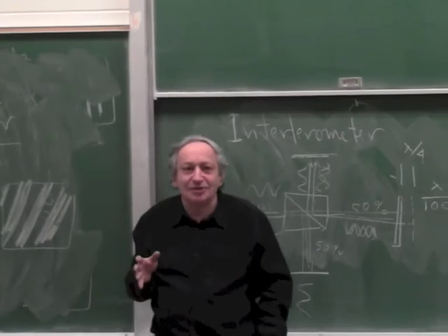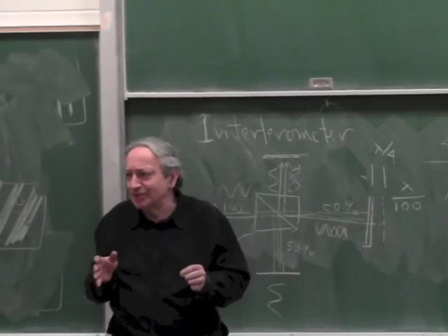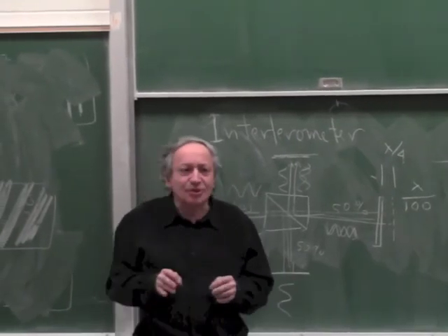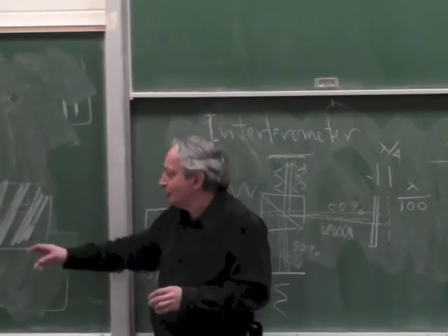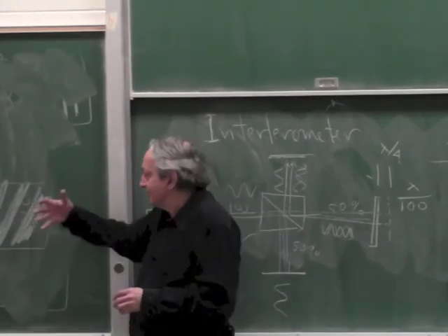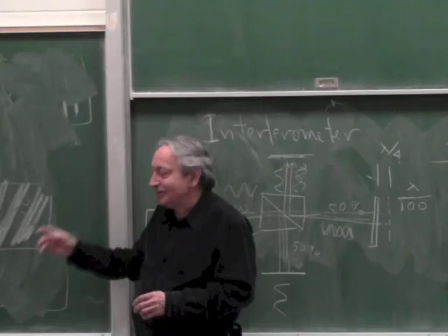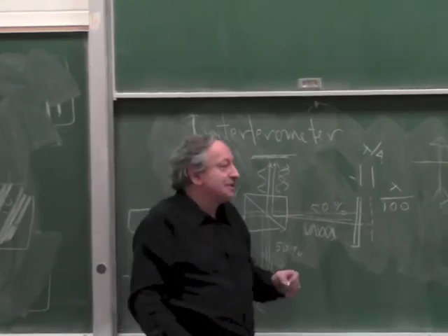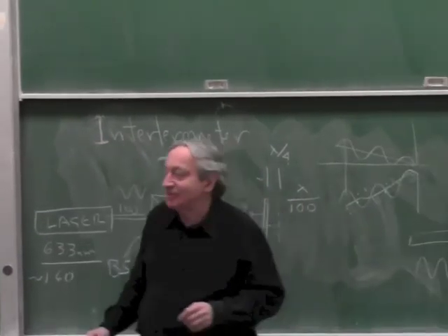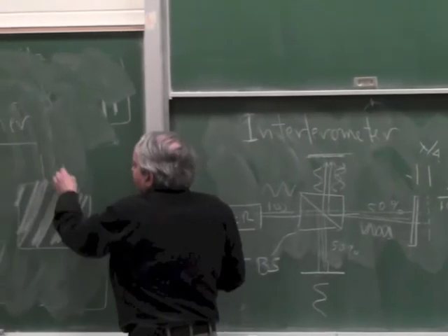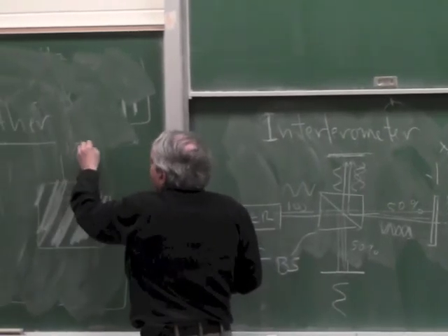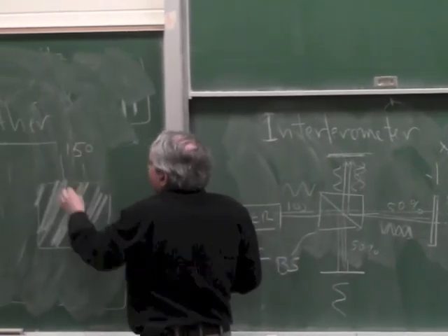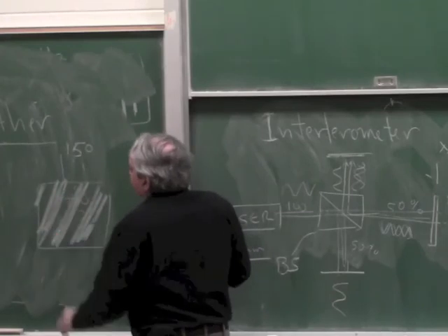Because with an interferometer you're not interested in very fast measurements, so the camera has enough time. So most modern interferometers actually don't put it through a split detector, but put it straight onto a CCD sensor. And you analyze it with software. And those ones can go to a nanometer. Because imagine, if a full movement is 150 nanometers, the camera can easily analyze 1% of that.